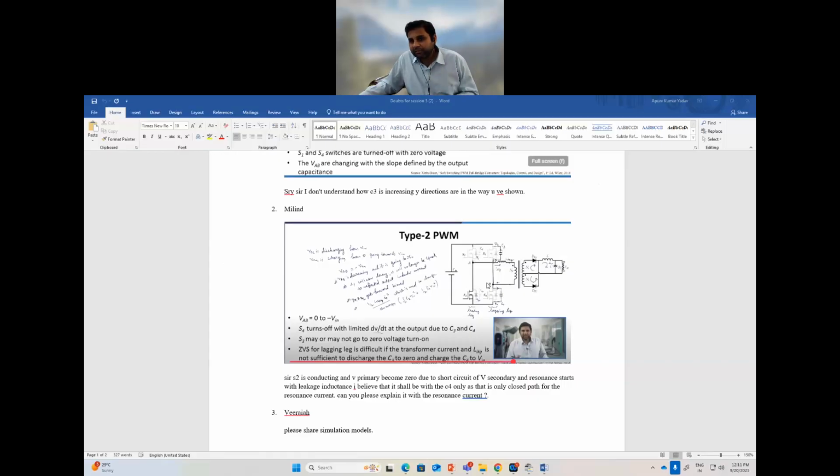However, whether it will be placed nearby or slightly far away, what I am trying to say is that this current is an enormously larger amount of current because it is reflected from the output side. Since this current is a larger amount and kind of a constant current because of the output current in the inductor, what you will see is that the effect of the bigger loop or smaller loop will not be that much as compared to when it would have been just the voltage source.